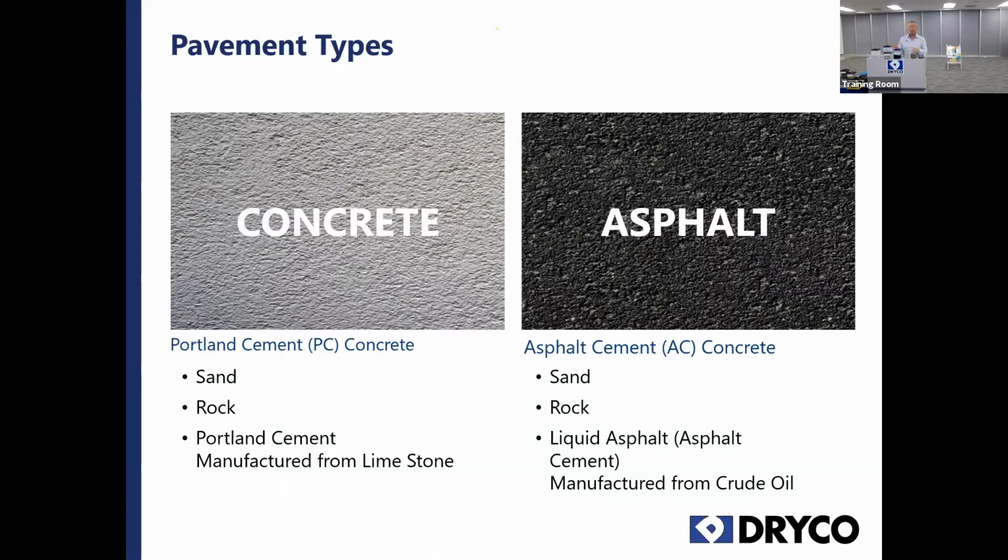job. Now I have 3 of the transit mixer trucks because it's hard to get materials and it just makes us a little bit more efficient. So it comes to the job, and then we lay it, we could pump it, we can shoot it, we can do whatever, we screed it, we finish it, and it sets up when it stops moving, right? So that's why it's in that mixer truck moving, is because as soon as it stops moving, it starts setting up. So it's kind of a chemical set.